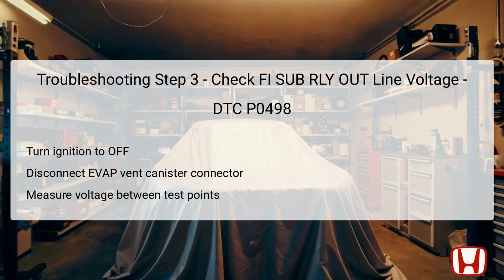Turning the ignition to the off position ensures that electrical loads are minimized and the circuit is safe to test. Disconnecting the EVAP canister vent shut valve 2P connector isolates the circuit from the component. Using a multimeter or HDS, measure the voltage between specified test points, specifically between the wire labeled WHT and ground, to verify the presence of battery voltage.